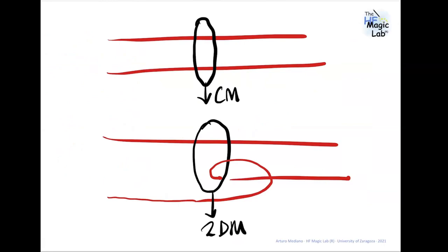This is the correct way. But what I was explaining is that depending on where the current probe is located, here or here or here, the measurements can change a lot because there is a transmission line and you have reflecting waves, and you can have maximums, minimums, zeros. So you need to keep the cables very, very fixed in position.